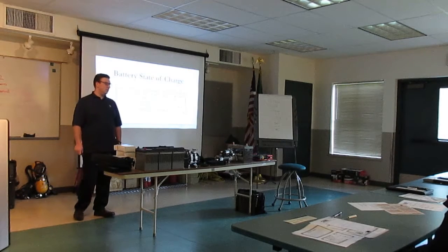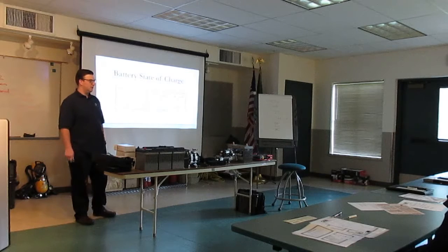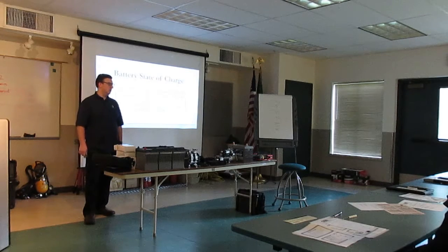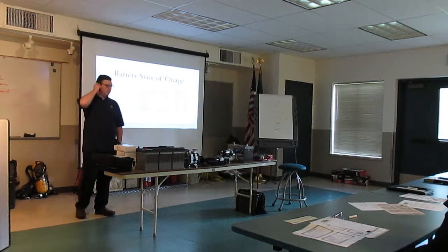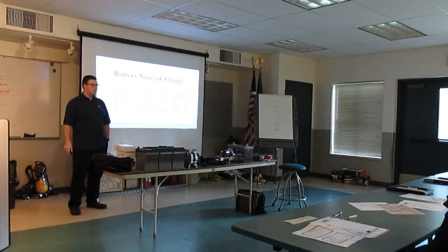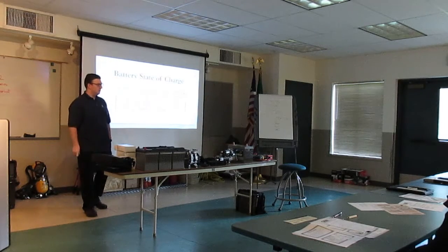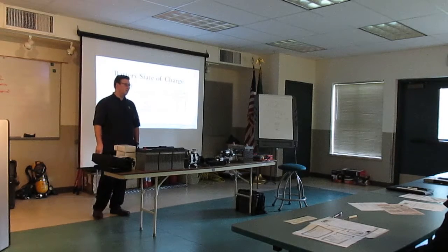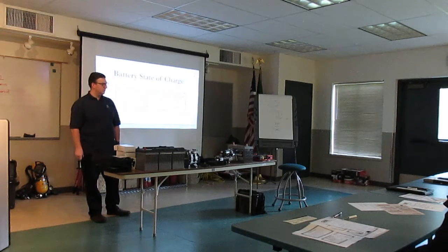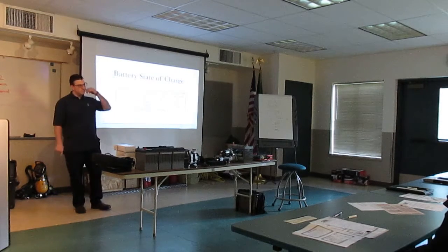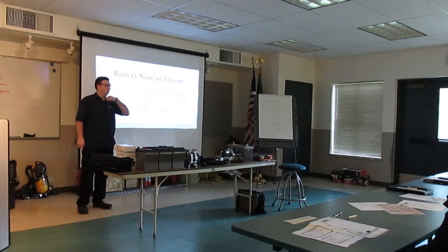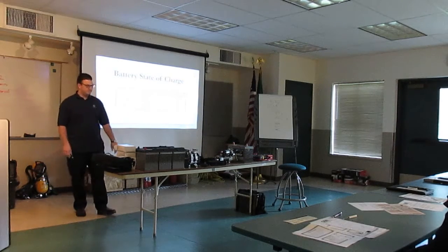Right? Okay, what is your parasitic load? Does anybody know on a truck? I mean, what do you got? Computer, charging flashlights, radios, apartment doors are open. Does anybody know what the parasitic load is? It's probably closer to 20. So if you have that 20 amp charger on your truck and your parasitic load is 20, are you charging your batteries? What I found out later too is you don't trust your charger because it says it's a 20 amp charger, doesn't mean. Oh, that's true. So in the perfect world. Yeah, so you're using less than that.